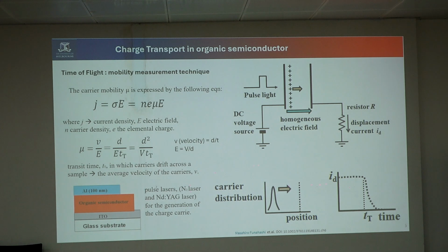So as I said, charge transport and finding mobility is very important in device fabrication. There are some other methods, but this is the most commonly used one. Some people talk about dark injection and electro-absorption spectroscopy. There are some other techniques that are not quite popular, but these three or four you can see in many papers, and these are reliable methods. SCLC is the most reliable method, and time of flight as well, to measure charge transport. Why is it very important? Because if you know the mobility, generally we can reduce the recombination happening in the devices.